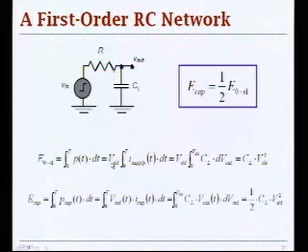If you go full swing from 0 to VDD, because you have a step input, you have VDD, and you need to integrate the current that goes through this RC network. You know that's equal to C dV over dt, so you end up with VDD times C dV over that period of time, which corresponds to a voltage transition from 0 to VDD.